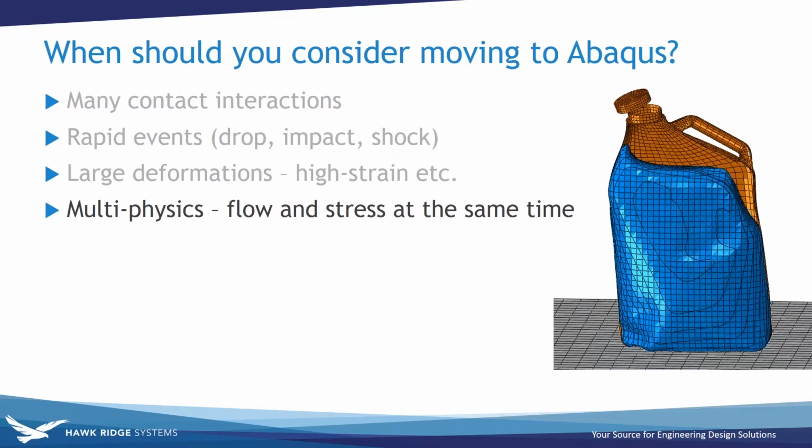There are built-in electromagnetic and coupled thermal-structural capabilities. There's a CEL solver for explicit that allows you to track the bulk fluid movements, the washing, and structural interaction. It's important to note that for problems like this, Abaqus is going to go about it by capturing the fluid potential, not the turbulence. So it's great for problems like the one on the right, but if you need full flow simulation, you can couple another CFD product with Abaqus as well.